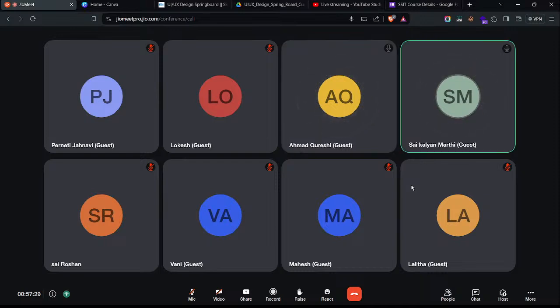If you work on the controller itself, you can understand the register mapping. So find some STM32 and start reading each peripheral. Start with GPIO, then timers, then UART, then SPI, I2C, and buy some sensors to interact with them. In this way, you can learn better. This is my suggestion.